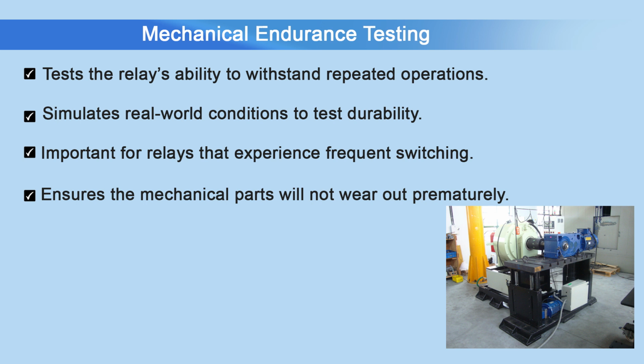This mechanical endurance testing is important for relays in applications with frequent switching such as motor control relays or lighting control systems. So, a mechanical endurance test might involve actuating a relay 1 lakh times and checking for any changes in contact resistance, timing or functional performance.